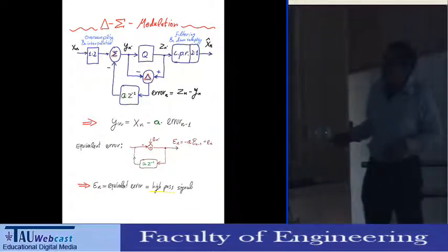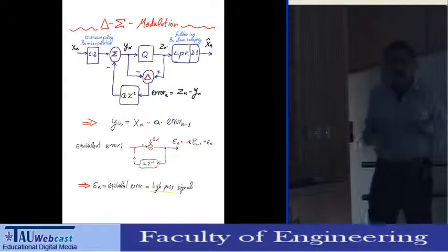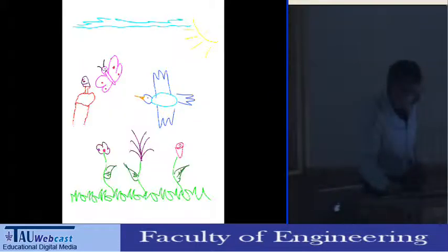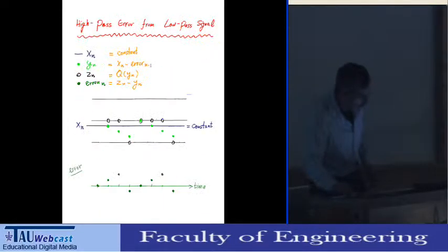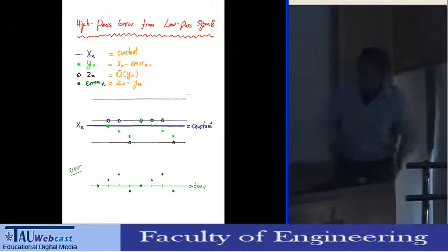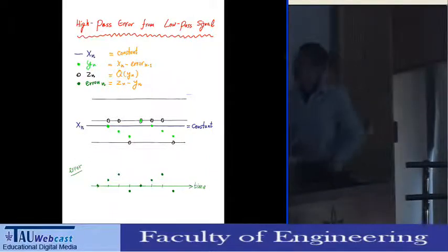Now I'm putting a low-pass filter and going back to the original sampling rate, and the low-pass filter will remove most of the noise. This is the nice idea of sigma-delta modulation. This is what happens when your kids see that you are drawing pictures on the computer.